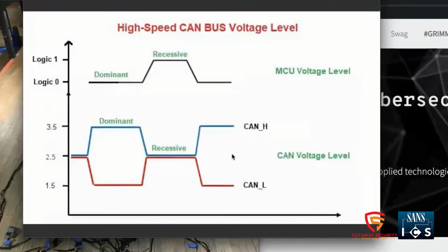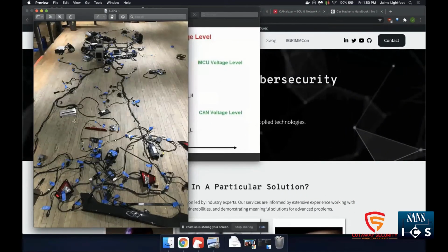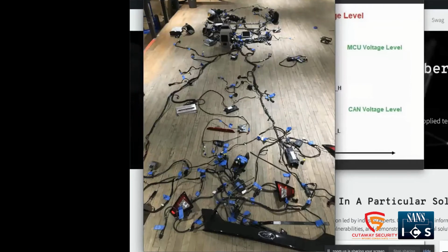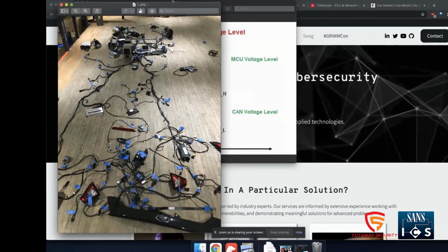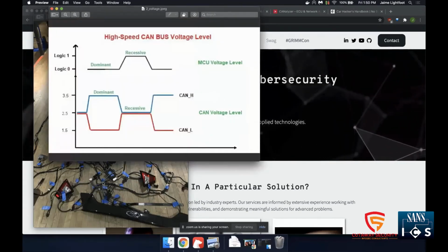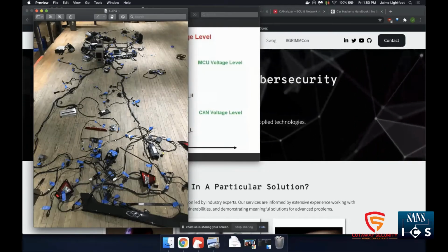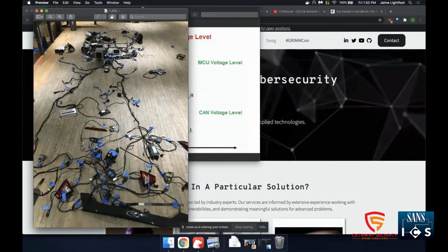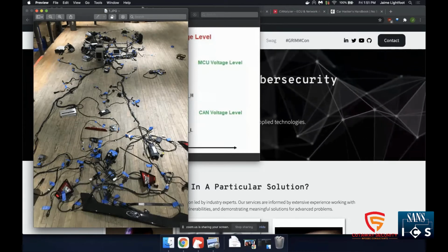Interesting. So for each of the components that you put on the CANbus, we talked about how you've got the audio, telematics, the different lights, the antennas. The more interesting stuff is, of course, farther away in the photo. But you want each of the devices to be able to plug in onto this harness and just be plug and play and be able to communicate with the other devices. So each device needs to have a CAN transceiver that can send messages out on the CAN high and CAN low lines. You need to be on the same speed. And in software, you have to have the same kind of concepts of what messages are being sent.